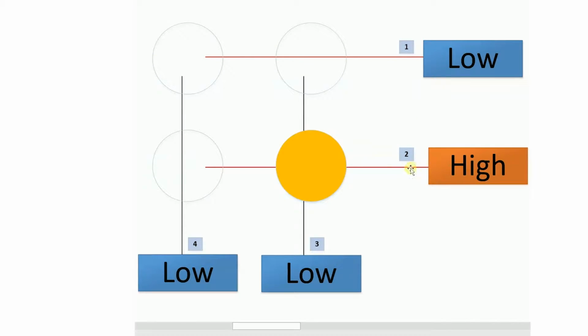And since we turn this row on, and this column is low, and this row is high, this bottom left LED would also turn on. So say we only wanted the column on the right to be on and the column on the left to be off, we would set this column to high.